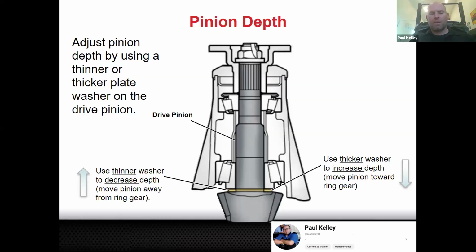So I'll give you a couple of options here. One, you take your old bearings, which are pressed onto the pinion, and you use a file or a Dremel or a die grinder to open those up so they're no longer a press fit. That way you can just pop the bearing on real quick, but that bearing won't be good for use.